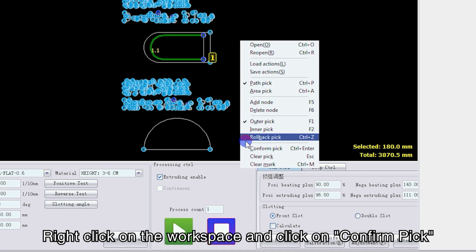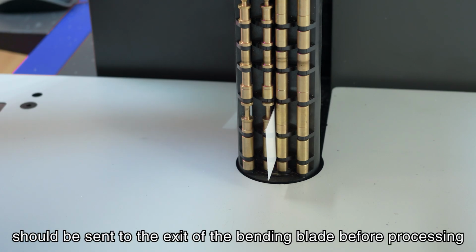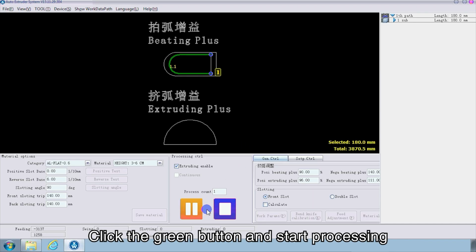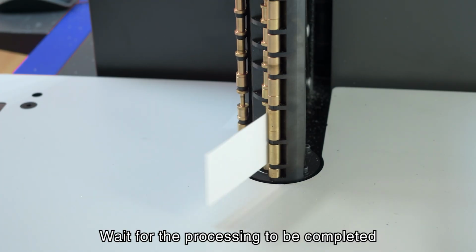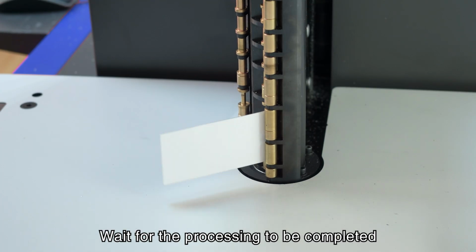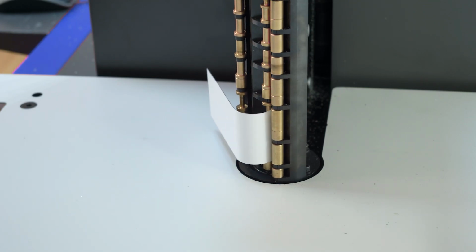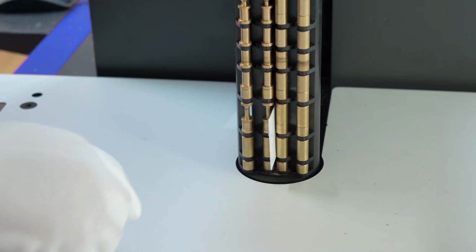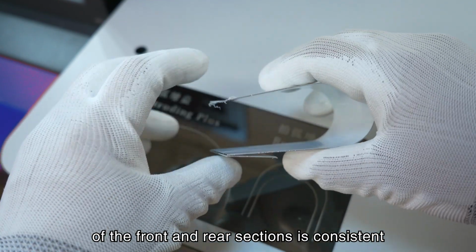Right-click on the workspace and click on Confirm Peak. Note that the sheet metal should be sent to the exit of the bending blade before processing. In the Processing Control panel, click the green button and start processing. Wait for the processing to be completed. Observe if the length of the front and rear sections is consistent.